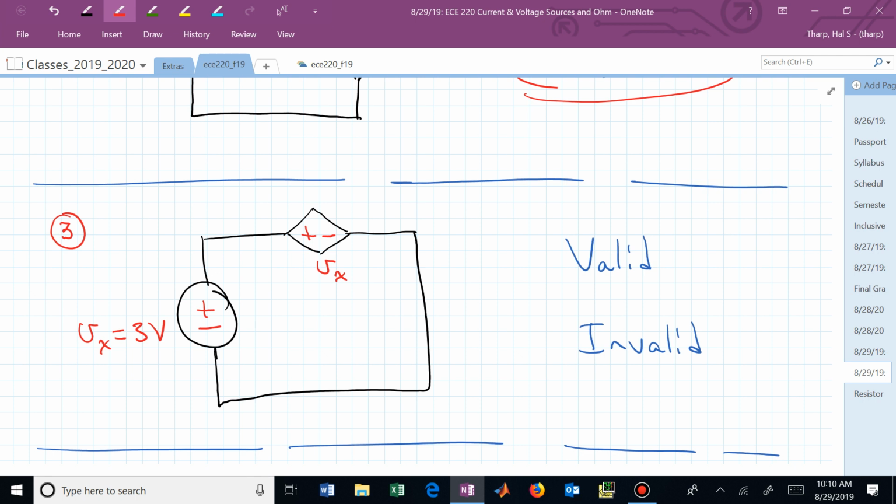And if you don't see it that way, the nice thing sometimes about circuits is you can stretch these wires or collapse them if you want. You could put that dependent source in the right leg or the right stem of that circuit if it wasn't visually appealing to you the way it's drawn here. Before, if you said it was minus plus and then it was plus minus, well, just bend that circuit around. Do you see what I'm trying to suggest? To where it looks like what you wanted it to look like before.